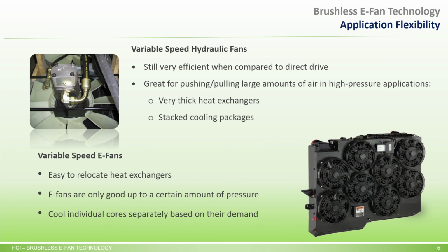Now that we've established that variable speed fan drives are beneficial, let's look at a few design criteria for hydraulic versus electric. Variable speed hydraulic fan drives are still very efficient compared to direct drives. They are also great for moving large amounts of air in high pressure applications, such as thick heat exchangers or stacked cooling packages. Now, variable speed E-fans are easy to relocate, but are only good up to a certain amount of pressure, so they wouldn't be able to accommodate a heat exchanger, say 10 inches thick.